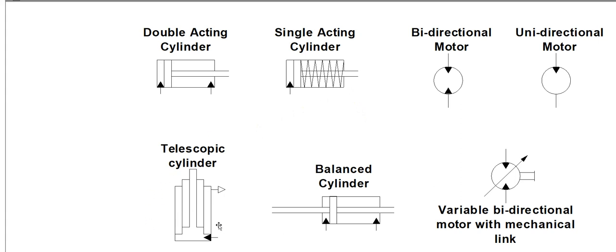Another type of cylinder we see is telescopic cylinders. This one here is just being single acting again. The solid arrow here pushing oil into the base end, and it will push the whole cylinder up until the first section bottoms out, then it'll go to the next section, and then the final section, just telescoping as it goes out. This little arrow here on the top, notice it is an arrow, but it's not colored in. So solid arrows indicate hydraulic fluid.